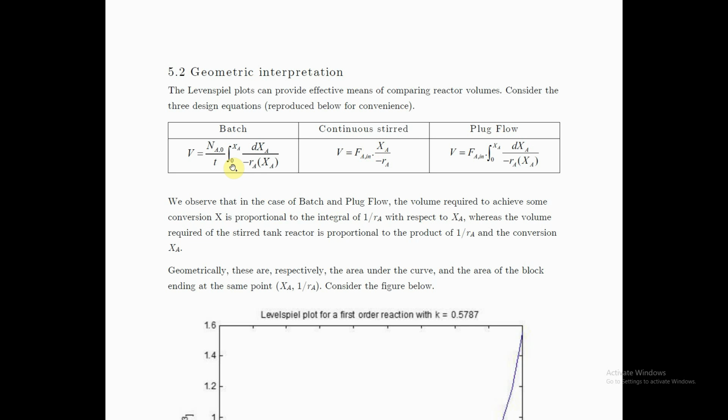In the batch case, you can easily create a batch reactor in the same sense as a CSTR. A batch reactor is perfectly mixed, and you can seal off any flow from happening. So you can construct a batch reactor. But we know that the batch reactor suffers from other disadvantages. It has continuously disrupted behavior.